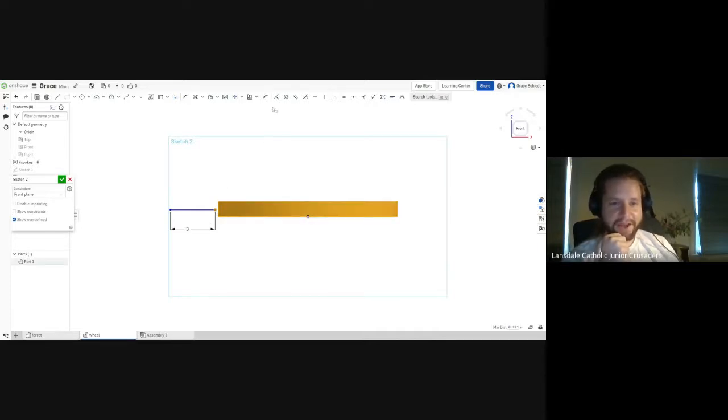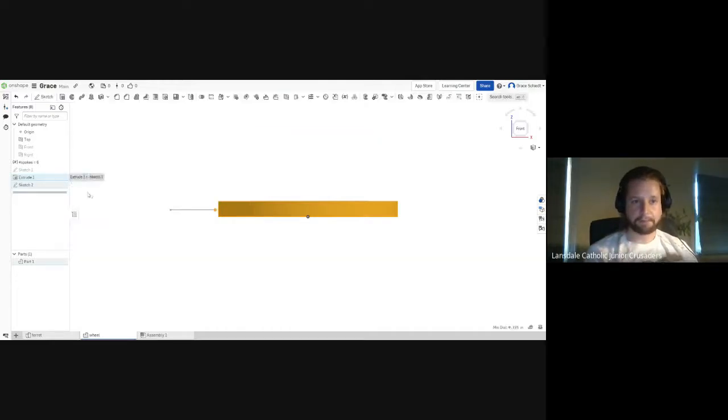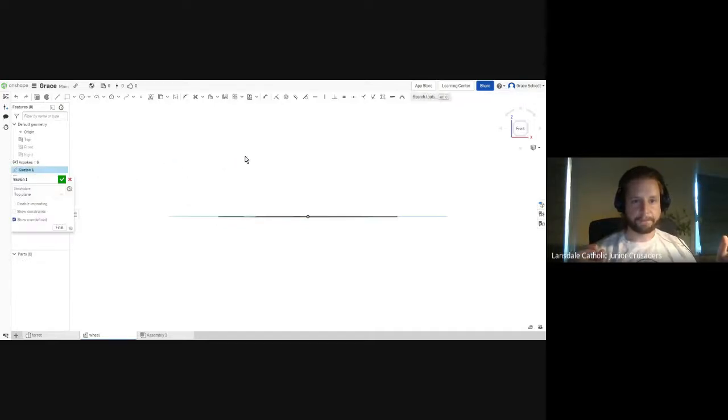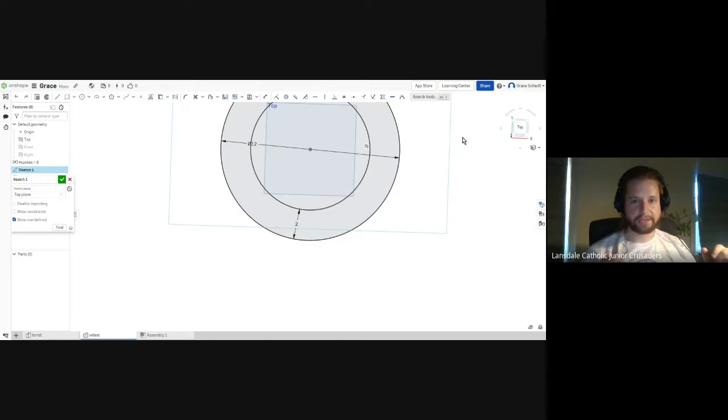And you have a round surface there, so you can't really constrain a point to a round surface very well, right? Yeah. But you did make a sketch that has a circle that you could potentially put a point on. So this is getting a little bit more complicated, but I'm going to walk you through it. I'm going to show you my rationale. I would finish this sketch as it is and leave it be, and we'll come back to it. I would go back into sketch one. We're going to be time travelers for a second. We're going to go back in time. All you need to do is double click to edit sketches. Go back and go normal to sketch one. Just click the N key.